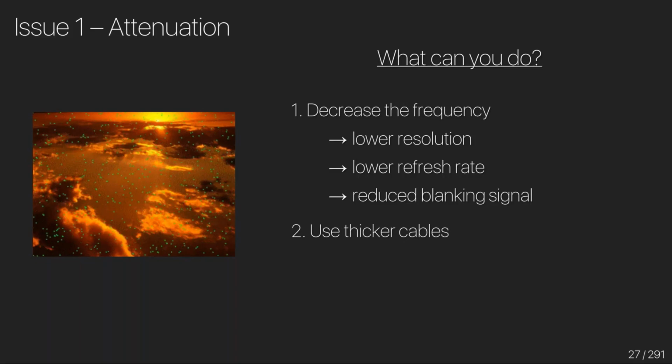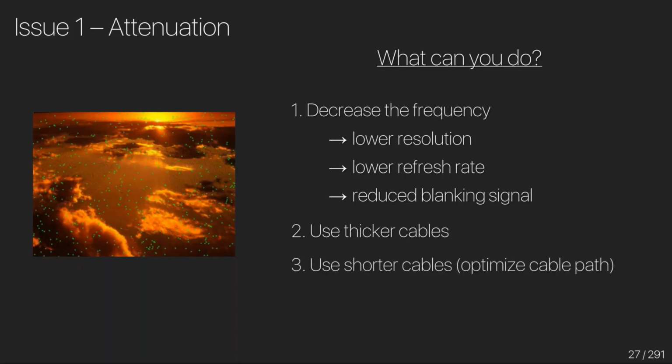Another option would be to use thicker cables, or even use a shorter cable and a more optimal cable path. However, maybe in the system you're working with, everything's already installed. The customer has a hard requirement for the resolution and refresh rate that you have to use. What can you do then? Well, you can use a technology called equalization.